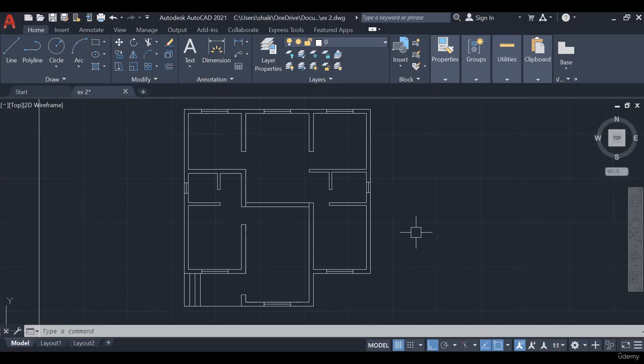In the plinth level, normally the plinth width is bigger than the side stone masonry or this wall. Correct? Because the foundation has a width, after that it will step and the plinth will come. The plinth also has a little width.